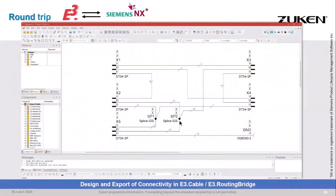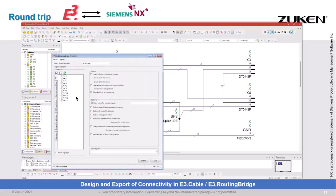So as I mentioned then, first of all, what we need to do is export our connectivity information. In this schematic, we have a number of connectors, we have splices, and we have an eyelet. From here, using the 3D routing bridge model, we are going to export all of our connectivity information, and that's saved as a PLM XML file that can then be read into NX.